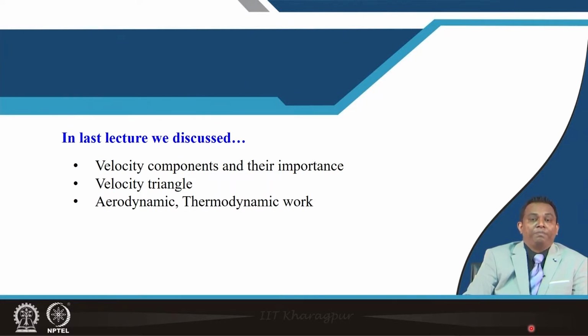Let me tell you, people have an understanding of the aerodynamics of an aerofoil. The fundamentals of aerofoil are applicable to this axial flow compressor, but you can realize this is not a two-dimensional body. Because of the variation of radius, our blade becomes a three-dimensional body. So the concept is applicable, but the whole flow physics, in the sense of aerodynamics, is totally different. It has nothing to do with the aerofoil we discuss for a wing. So from now onwards when I say aerofoil, be clear that we are talking about the aerofoil used for an axial flow fan or axial flow compressor.